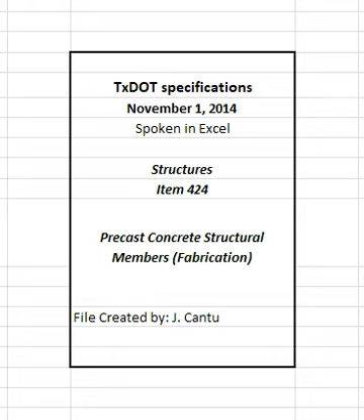Membrane curing is permitted on non-stressed members, except for surfaces to be painted or color stained. Cure members for an additional 24 hours beginning immediately after the normal curing period if they are out of cure at any time other than during the allowable 60 minutes for form removal or during the allowable 4 hours for moving piling to storage. Members failing to meet the concrete temperature requirements or curing enclosure air temperature requirements during curing will be reviewed. Repeated failure to maintain proper concrete temperatures may be cause for rejection of the affected product.